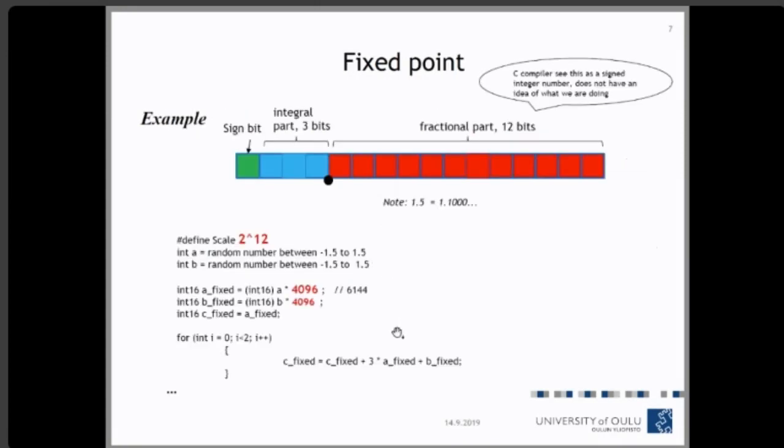As I mentioned, you can face overflow in such operations. So when you are doing fixed point, again you have to analyze it as a programmer. But most of the time, when you are doing fixed point operations, you have to scale down after operations such as multiplication, because here you have a fixed point number that's multiplied by another fixed point number. In this case, of course, you have a constant that is multiplied by a fixed point number.